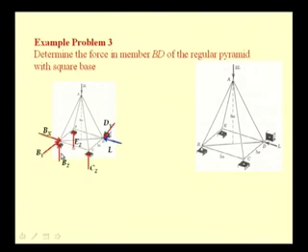If we see the joint at B, we have to determine 3 unknown reactions and then the various forces, that is BC, BD, BE and BA. At D we have to determine only one external reaction dy and the forces in the members AD, CD, BD, ED, etc. At D we see that we have to determine forces in 4 members, and in order to do that we need to know at least one force if we have to use the equilibrium equations of joint D.